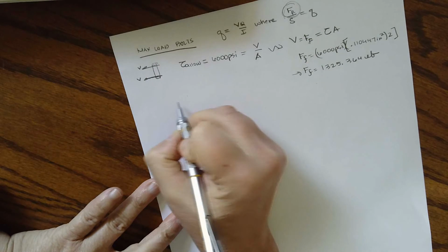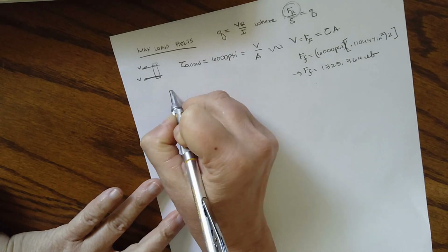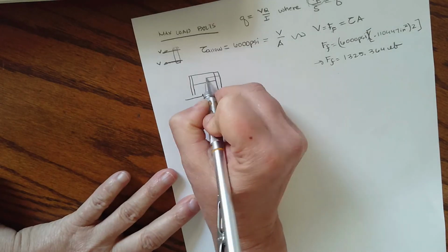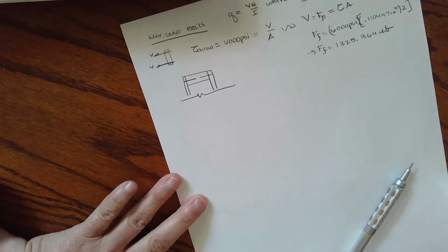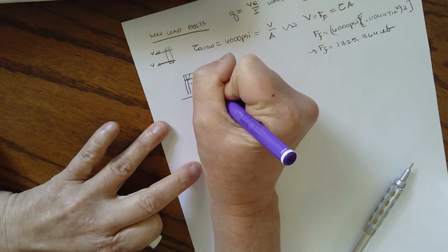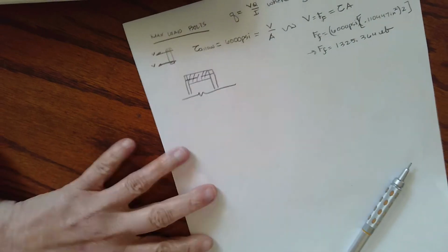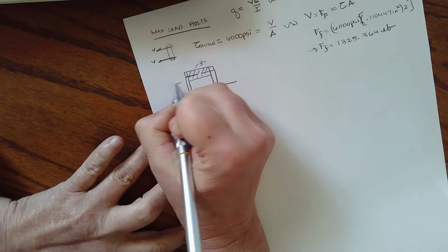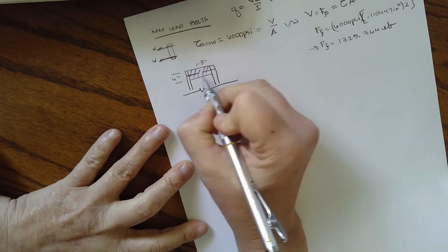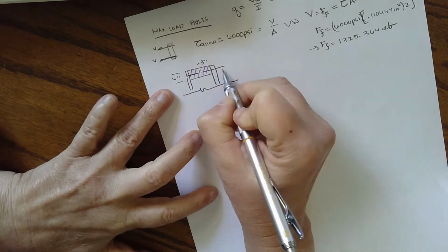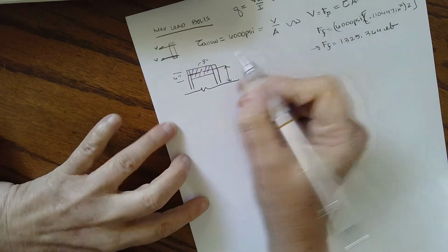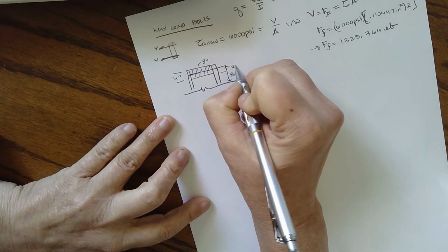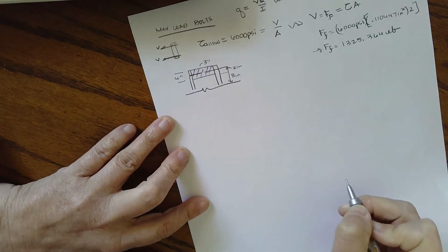And now we've got to go back and figure out Q. So we're going to draw another little cross section here, and we're going to figure out what our Q value, centroid, is. Our bolts are coming in sideways, okay? They are literally attaching this piece of lumber. The area of this lumber is 3 inches by 4 inches. And then the centroid is going to go from the centroid of that lumber back down to the centroid of the hole. And we already calculated that it was 8 inches up. And then we're going to go up 2 inches because it's 4 divided by 2 to get to the centroid.